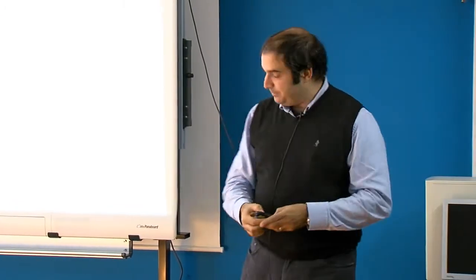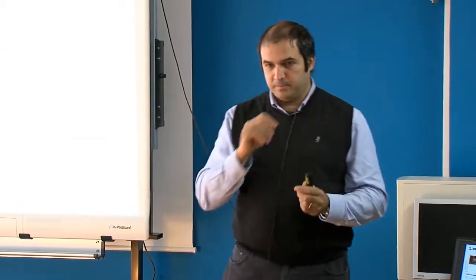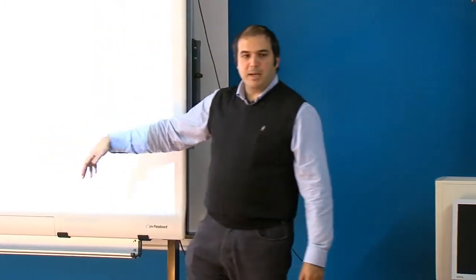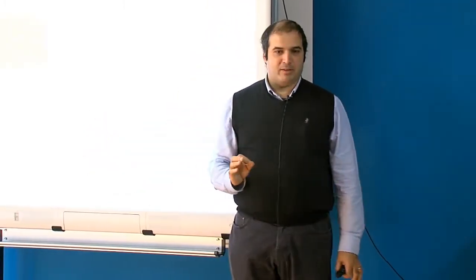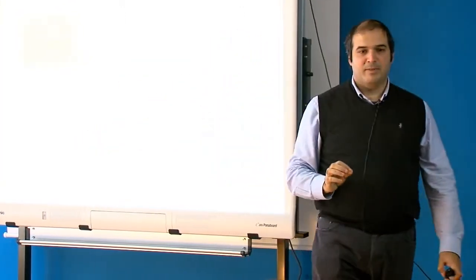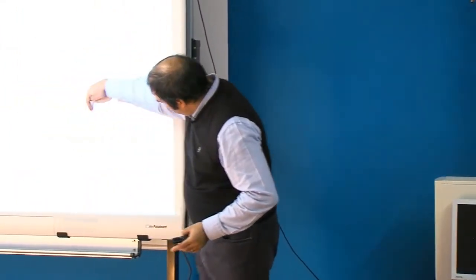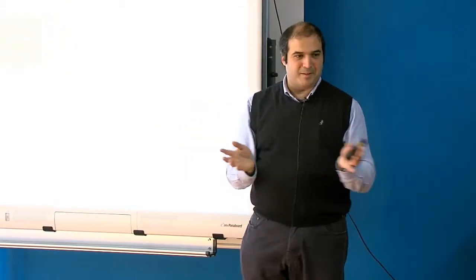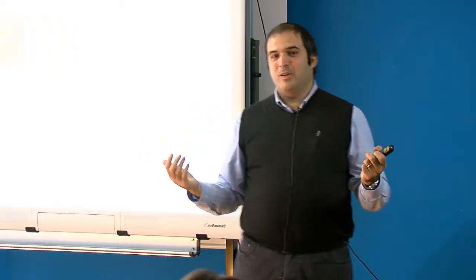Then I go to the lab and create another signal, a wideband CDMA, so something like 3G if you want, with exactly the same spectra. You see, it's the black curve, exactly the same spectra. I pass it through my nonlinear device and go to the output, and the output is completely different. You see the output: the gain is the same, the linear part is the same, but the nonlinear part is completely different.